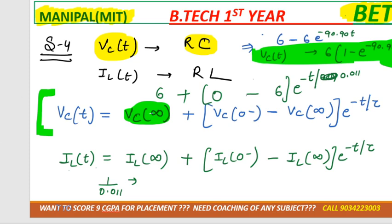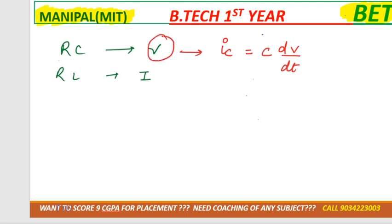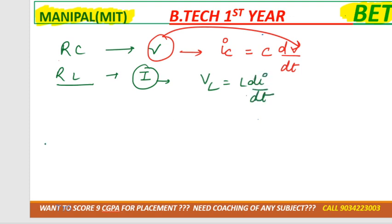I told you that if it is an RC circuit, voltage will always be found, and if it is an RL circuit, current will be found. But if they ask the opposite, like in an RC circuit they ask you the current IC, you need to apply the formula IC is equal to C dV by dt. Whatever the value of V, you will get it, substitute it here. But in an RL circuit, if they ask you the voltage, then the voltage across the inductor formula is L di by dt.